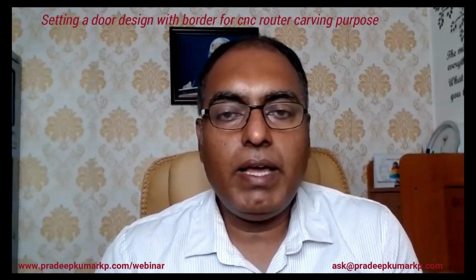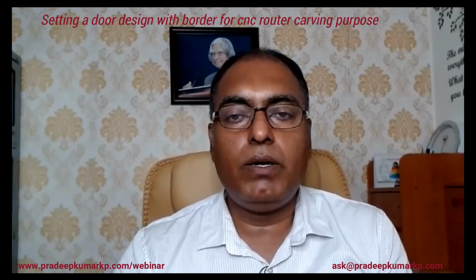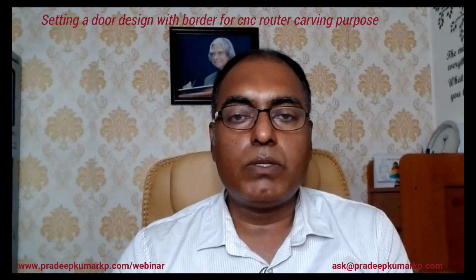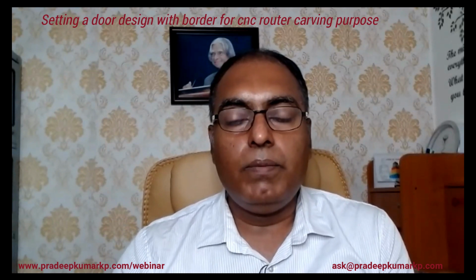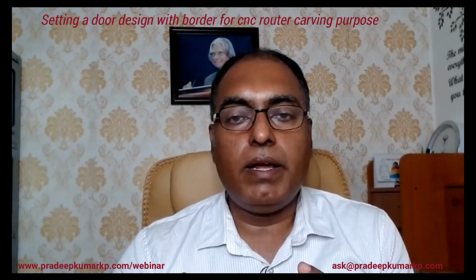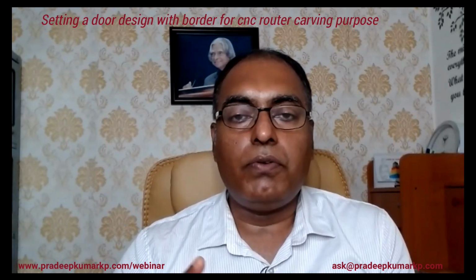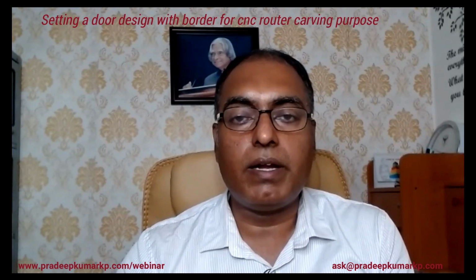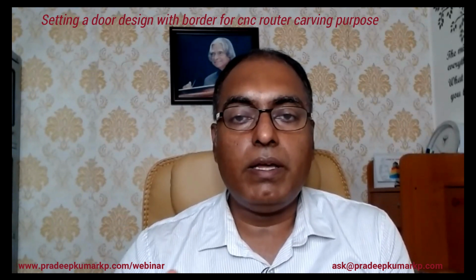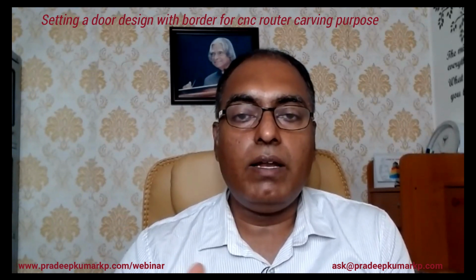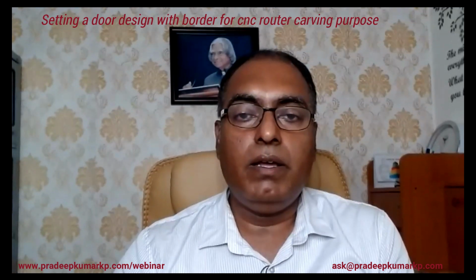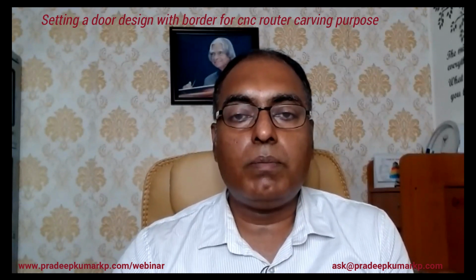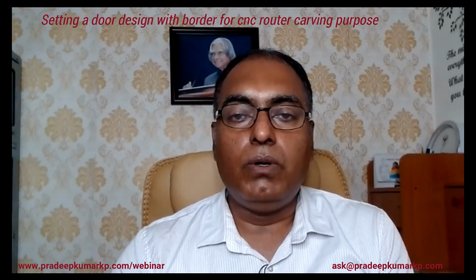Namaste. Today I will be explaining how to set a door for carving purpose. For that, I am using a software known as ArtCAM. In that, if you want to design a door for a particular size, how we will set the size; if we want a border for that design, we can create a border; and also how to import an existing relief file, make the design for machining, and do the machining. So this is the process we are going to look at today.